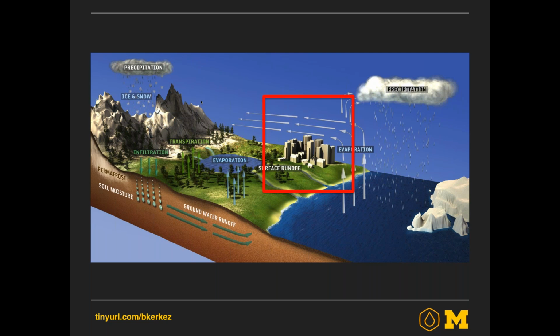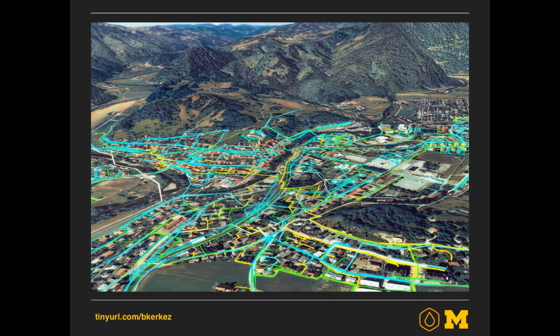If you zoom into this region, what you'll see is that urban water systems, as was well pointed out during the last session when Randy presented, are complex systems that involve natural hydrology but a lot of human-made plumbing. Your average city, even for very small communities, is underpinned by hundreds of linear miles of pipes and tubes that span the city, delivering things like drinking water, but also, in the context of today, serving stormwater management and sewers.